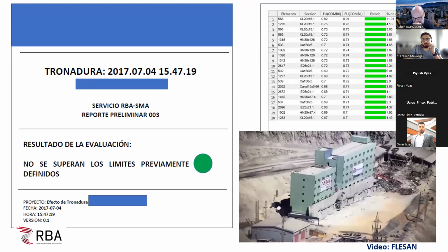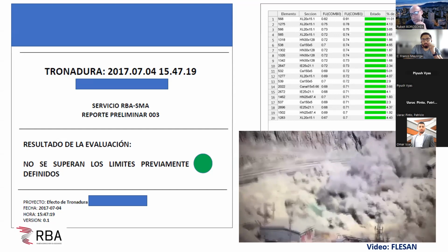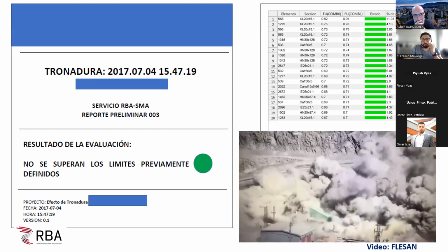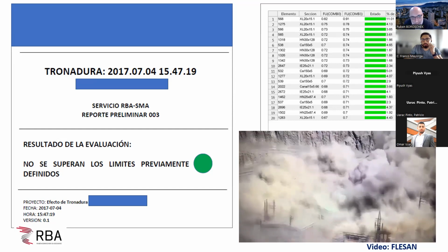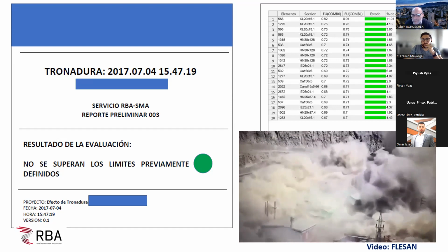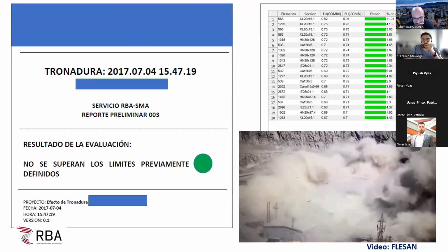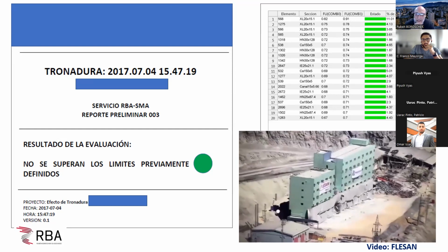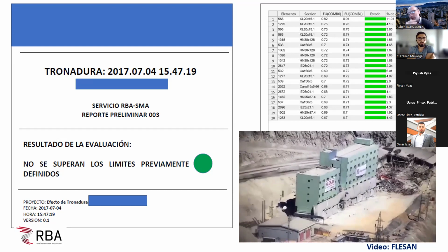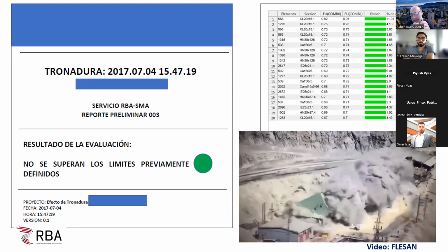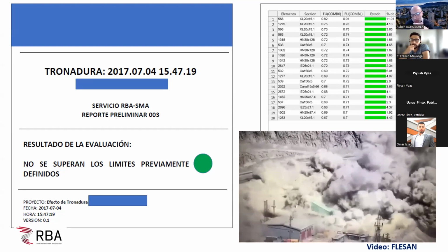Of course, in this case, you need a lot of money to have a 24-hour engineer just looking at this, and many sensors installed in the structure. But for a mine company, this is nothing compared to the production. Actually, the production was increased for this mine. Because of the limitations on this building, which was an administrative building, hotel and a restaurant, they thought they had to slow the production, and they realized that with the system, we actually changed the blasting sequence, so it didn't affect the structure as much. So they were able to increase the blasting loads and have a higher production than predicted.